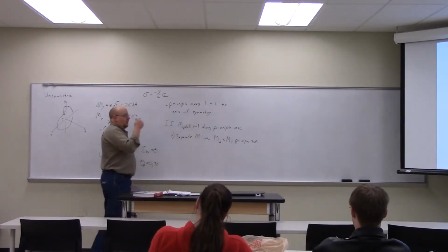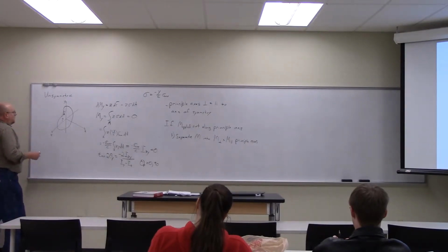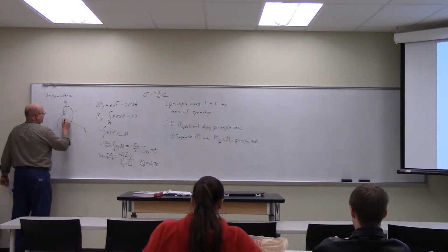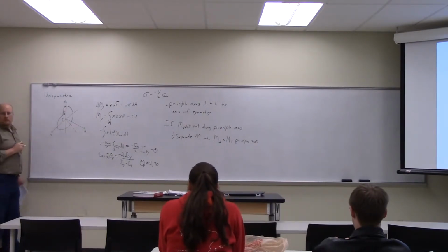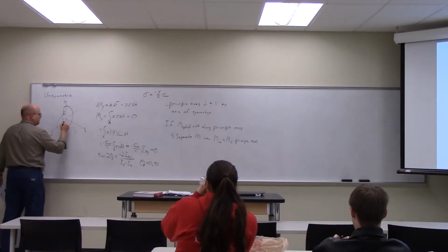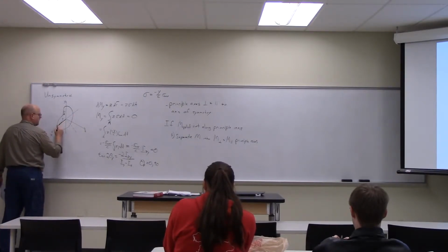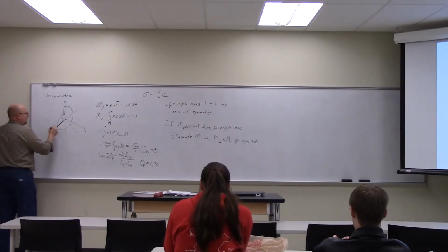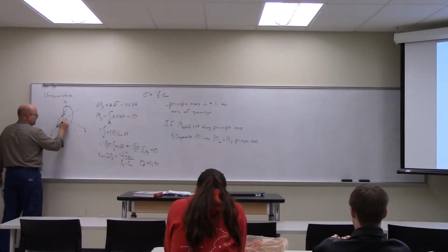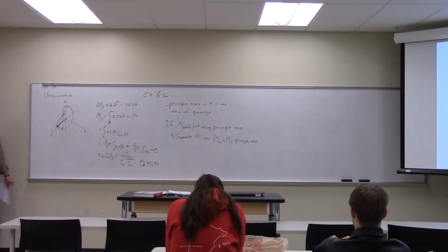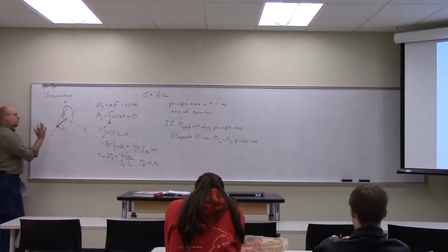So in this case, let's assume this is not symmetrical. If we had an axis of symmetry that was up here somewhere, and we're applying this moment, this z moment, that's our applied moment. We want to break it into a component along the axis of symmetry and a component perpendicular to that axis of symmetry. You can see what I'm drawing up there? So I'm applying the z moment, I'm bending this beam,